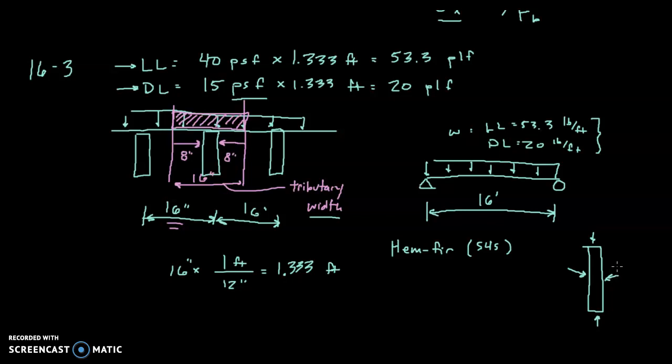Most lumber used in construction is S4S, but it doesn't necessarily have to be. You can purchase lumber that is perhaps surfaced on only one side, or two, or three, or maybe it's completely rough sawn. That's going to affect the dimensions, which will affect the strength of the timber, so that's why it's important to know that it is S4S.